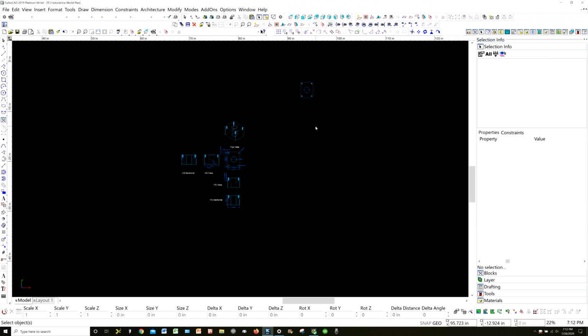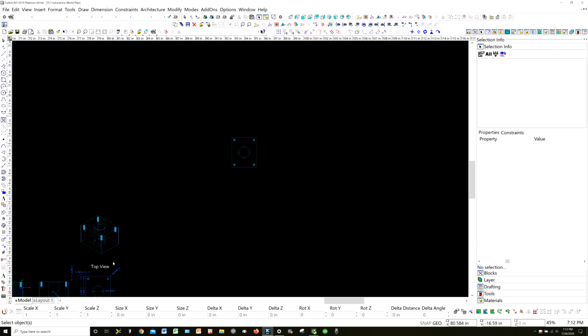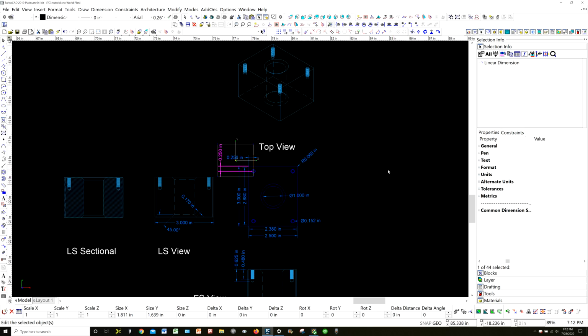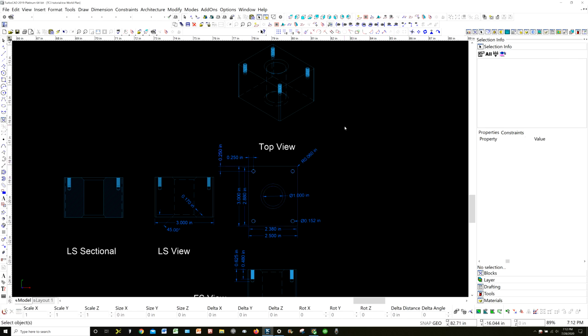Oh, I wanted to show you, when I was selecting something here, I believe it was down here. Okay, you see I have multiple selections here. So do I want the actual 2D object or do I want the linear dimension? Well, I wanted the linear dimension in that case. Now, make sure that that's actually set up correctly.